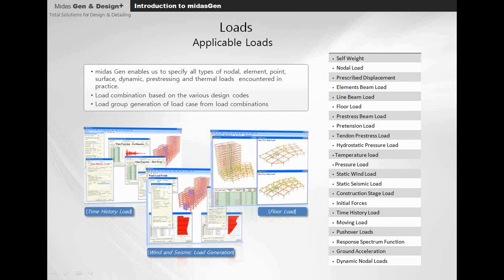Now, moving on. MIDAS 10 also enables you to specify all types of nodal, element, point, surface, dynamic, pre-stressing, and thermal loads encountered in practice. You can see on the right side of your screen some of the loads that are available in MIDAS 10. You can also input time history loads, and static, wind, and seismic loads. We also have provisions for dynamic analysis, like dynamic nodal loads, and for construction stage.